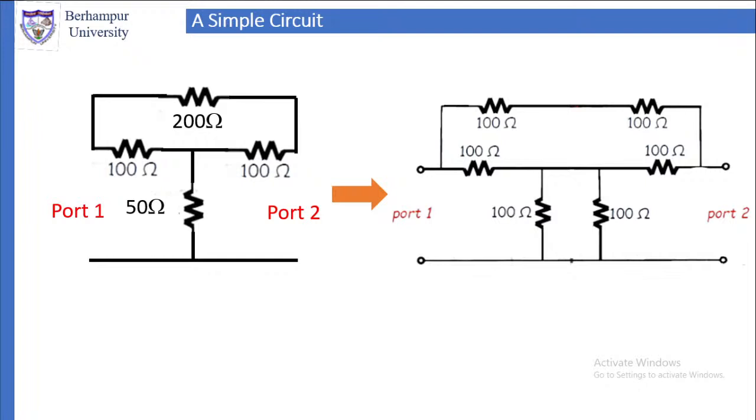In this circuit we have 200 ohm resistors in series, but in between them there is a shunted 50 ohm resistor, and across these 200 ohm resistors there is a 200 ohm resistor. If you look at this from the center, it looks symmetric, but at the top there is a 200 ohm resistor that is causing some asymmetry.